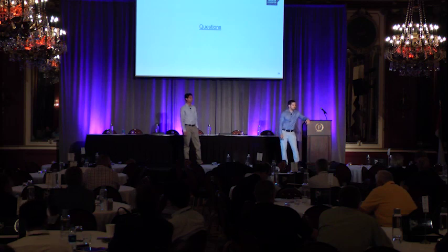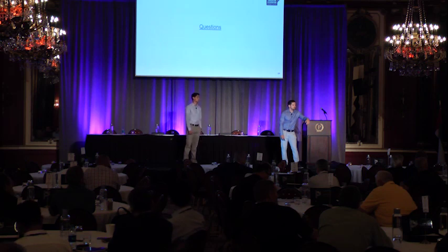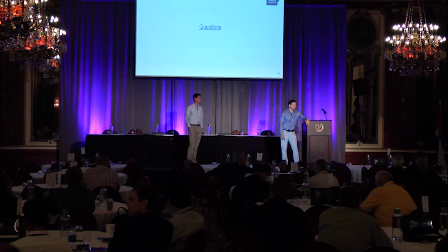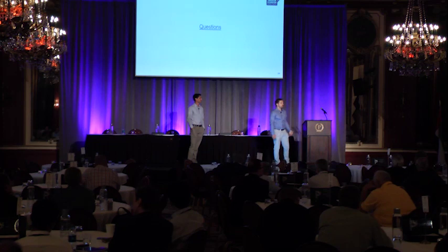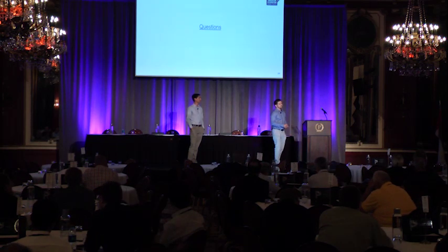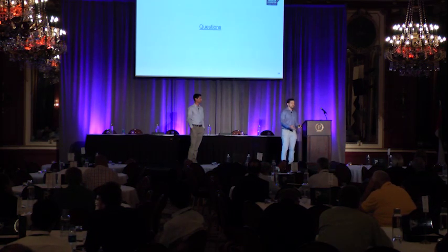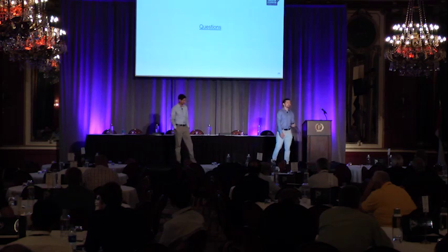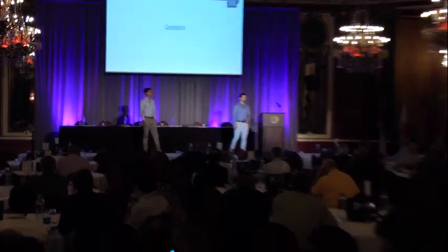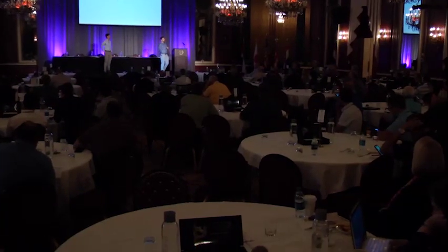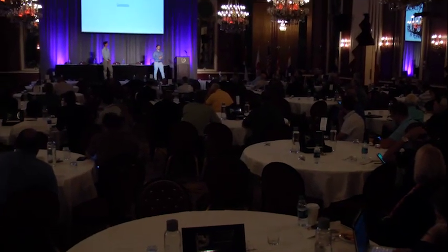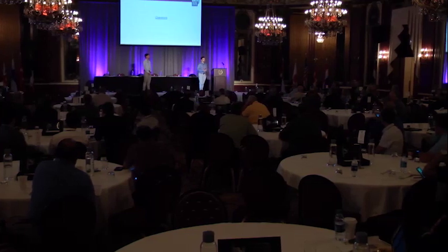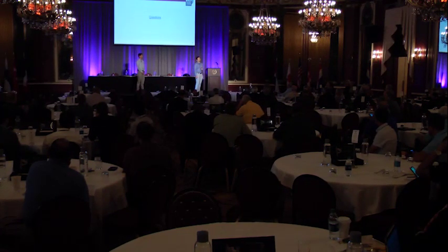A lot of times on existing structures, we have engineer of record issues finding the drawings. Yes, when it's required, we will do that. We obviously prefer as-built drawings. Well, first in line, we prefer that the engineer of record takes responsibility for his structure. But if that's not the case, we'll go to as-built drawings. And if those aren't good enough, hopefully we can resort to you guys being out there, FaceTiming, taking pictures, and then last resort is we'll go out and check it out ourselves.